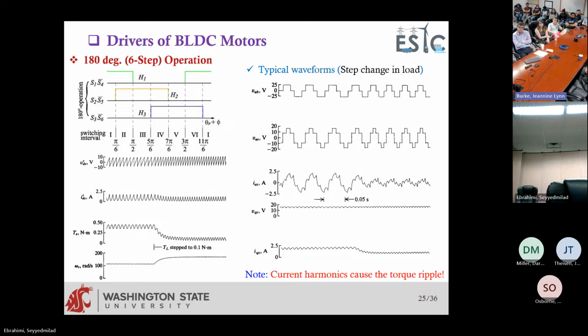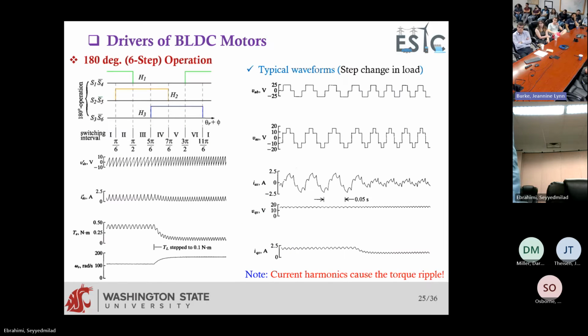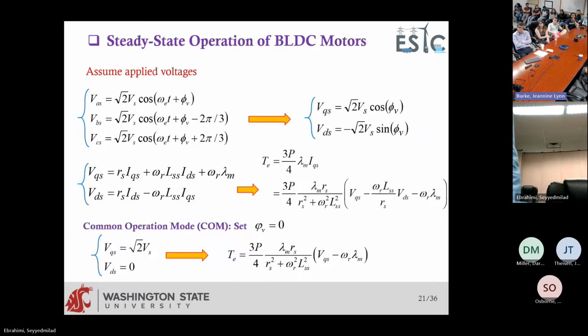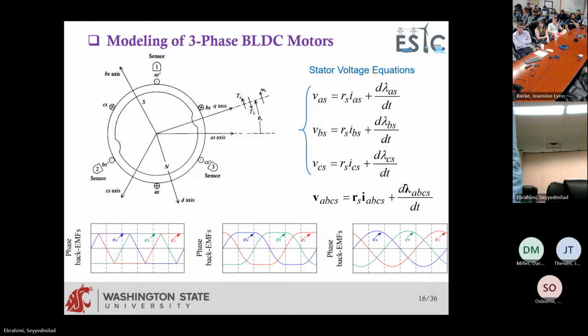The other cause of this imperfection is that even if you were able to produce completely sinusoidal voltage, which is not the case here, even if you use space vector modulation, it is just a very high switching frequency, which will be attenuated by the inductance of the winding, right?